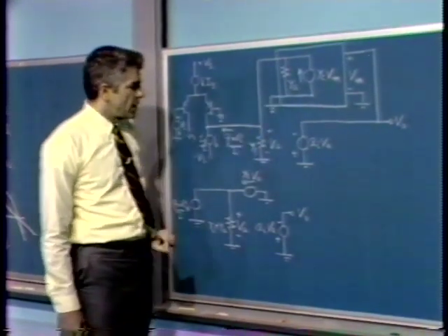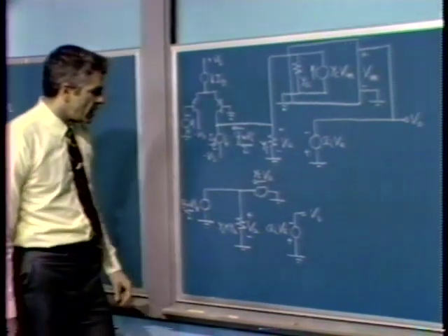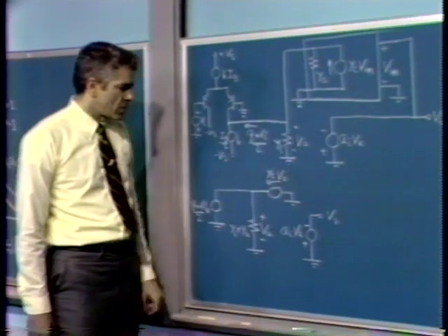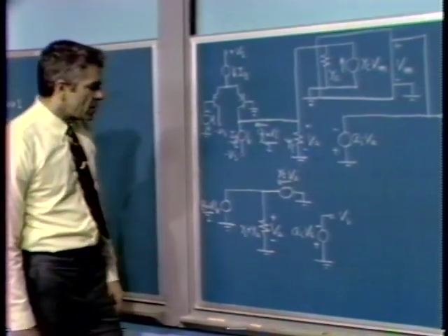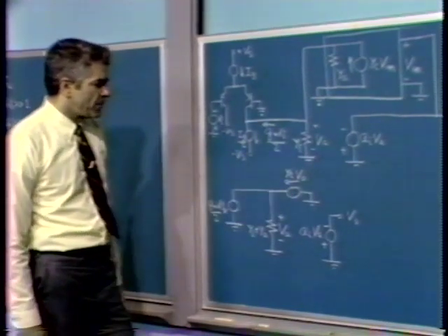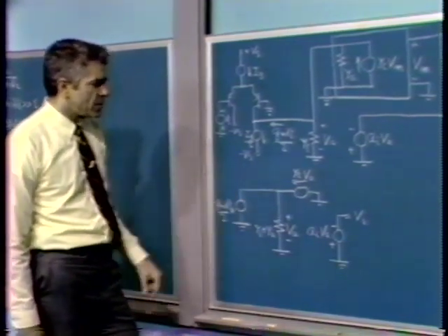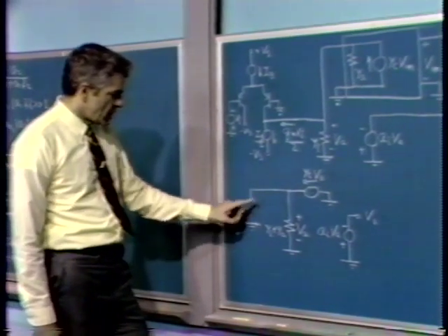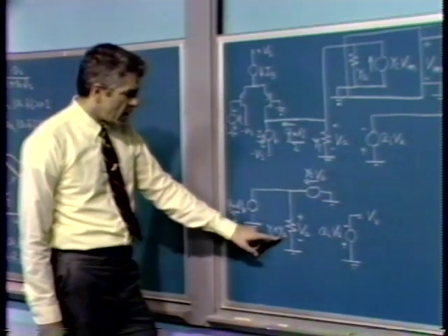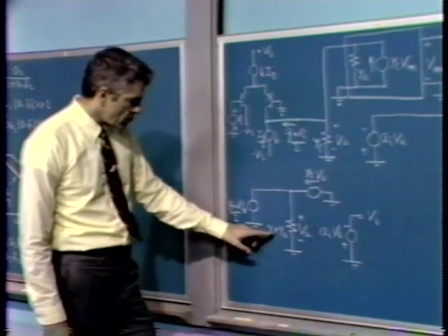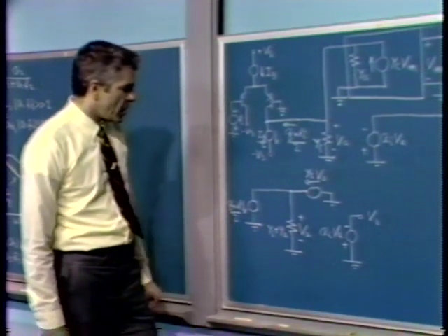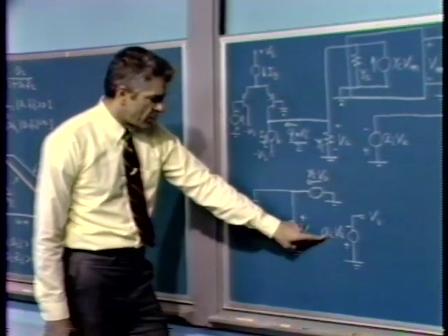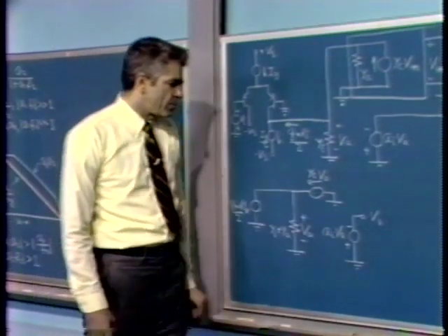We lump that admittance Y sub A with Y sub I to say all we've done really is make YC, or the magnitude of this generator, equal to 0, and then calculate the gain that results in the absence of minor loop feedback. Disabling this generator effectively makes F in the minor loop 0. Well, the gain would simply be GM over 2, that gets us to a current, times YI plus YA, divided by YI plus YA. That gets us the voltage at this point. We multiply that voltage by A sub I to get the overall output voltage.